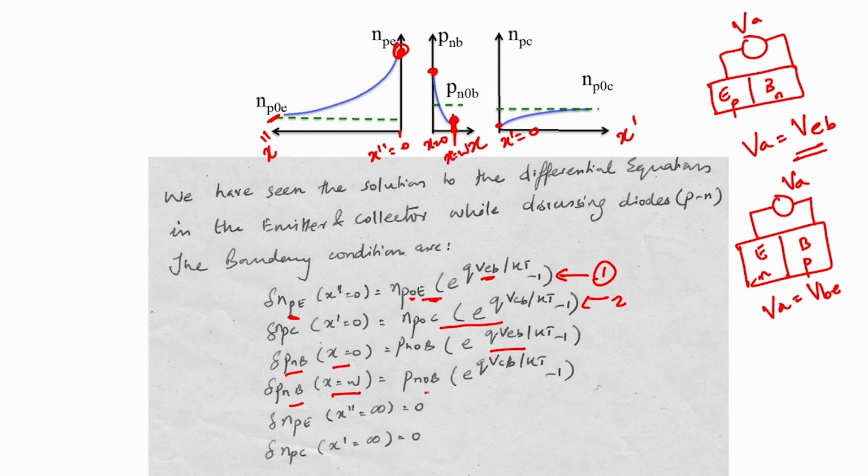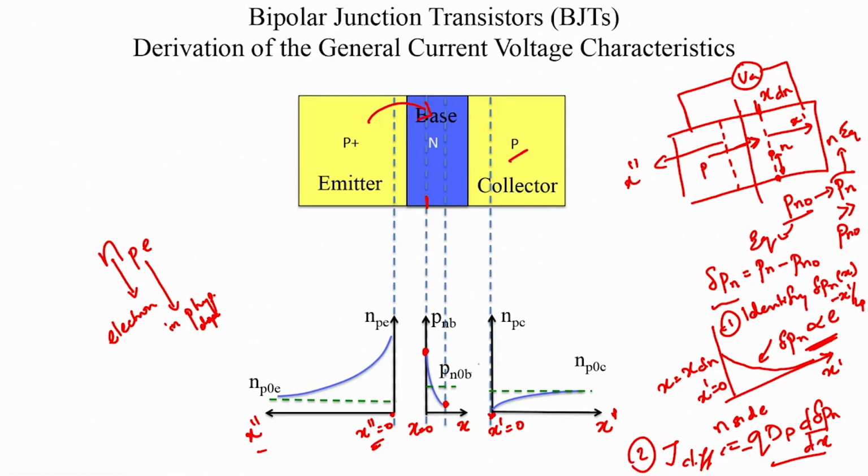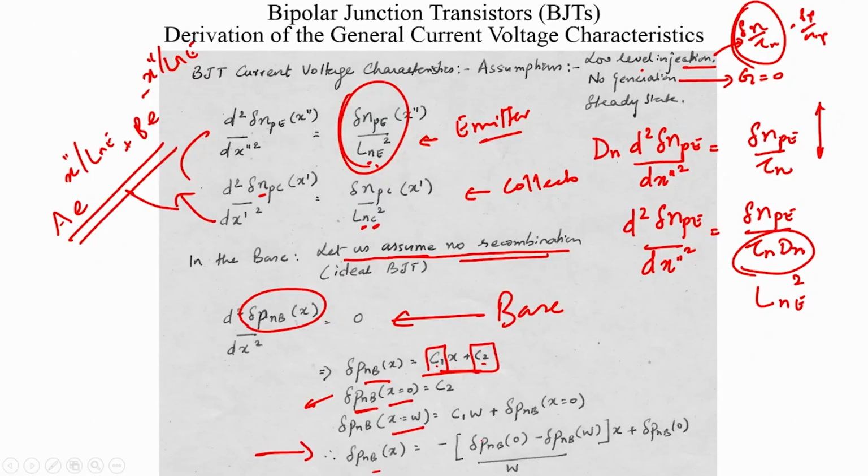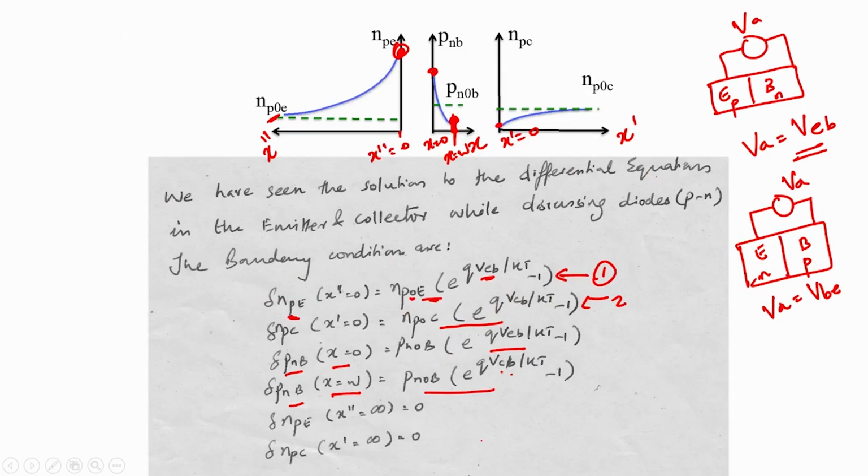That is given by the collector base junction, because that boundary is now at the collector base junction interface, it is at this interface. Okay, and therefore, that is my x equal to W, and since that junction is reverse biased, you see that this value takes this particular nature.